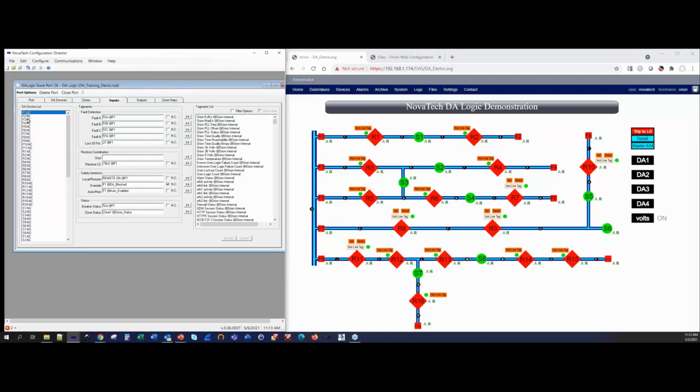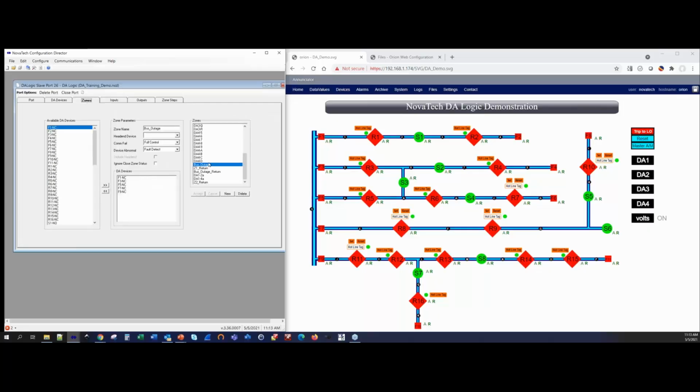So here's 1, 3, 5, 7, and 9, and they all have a 27 element, or an under voltage, tied to the loss of potential. In order to identify a fault within this zone, that loss of potential input has to be true on all 5 of these devices.